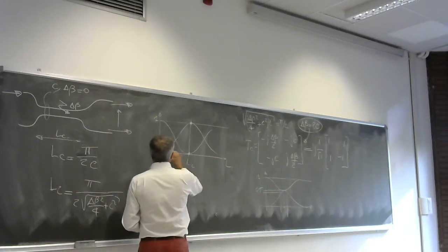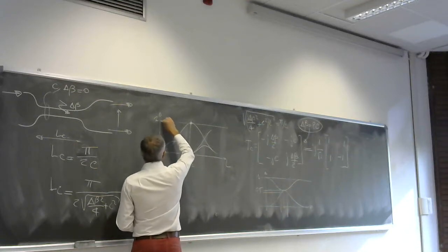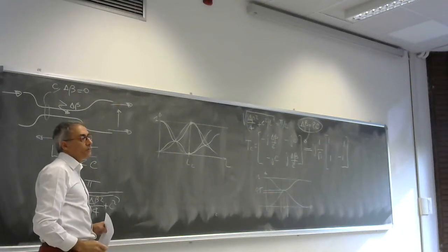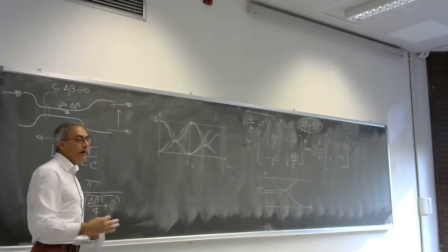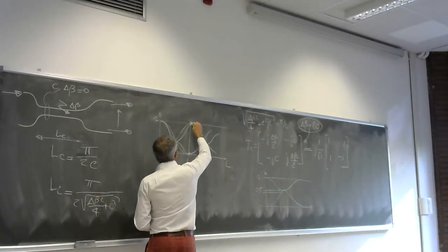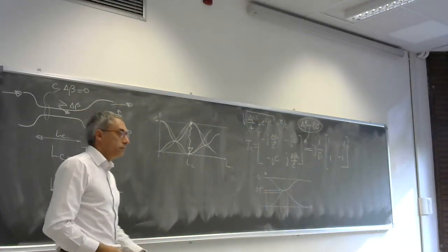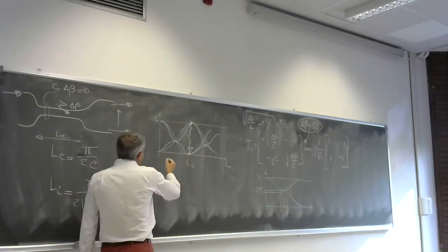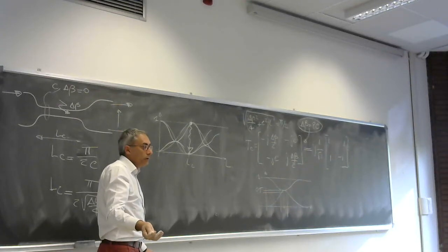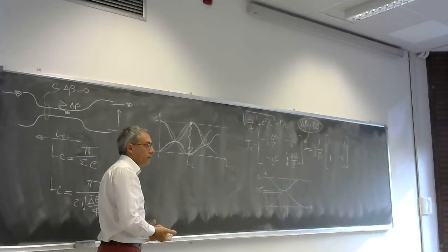And what you want is this. So you want to halve the coupling length. So you can move from one waveguide to the other. The coupling is no more 100% because it is asynchronous, and you want to reduce by 1/2 the coupling length.